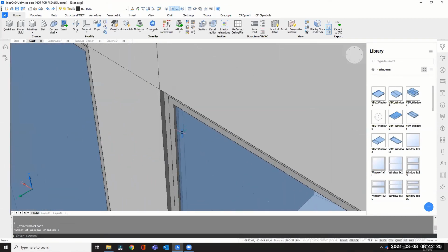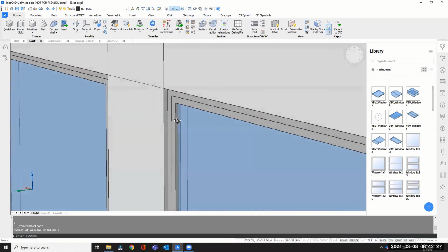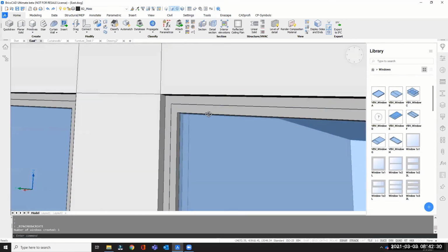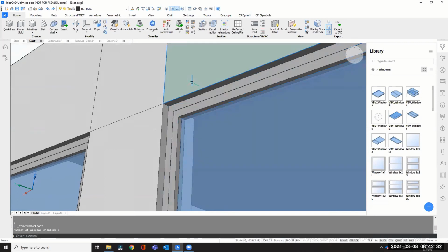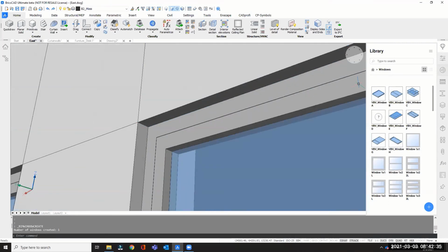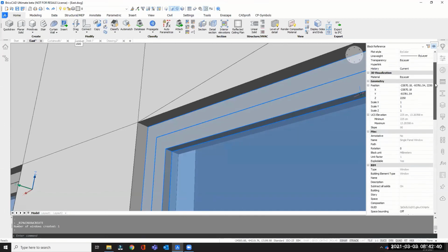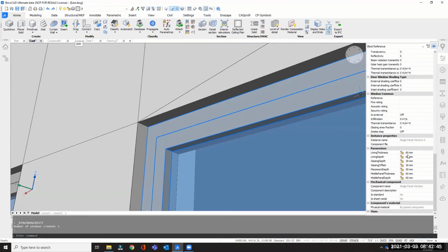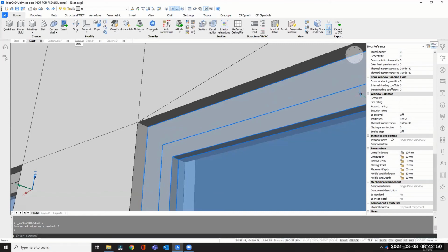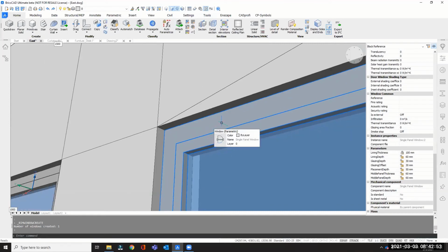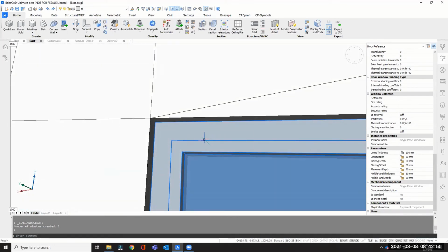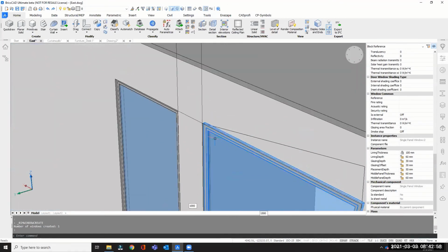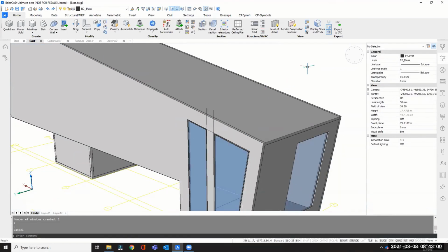So this is pretty good when your customers are rushing to have visualizations or just wanting to see very quick views of their design. If you see here, each window is actually also having some properties. Go to properties. You would find some information here. Maybe let's go to lining thickness. And if you just change something there on your parameters, you would see that it's also changed live for you on your model. So that's creating the window.